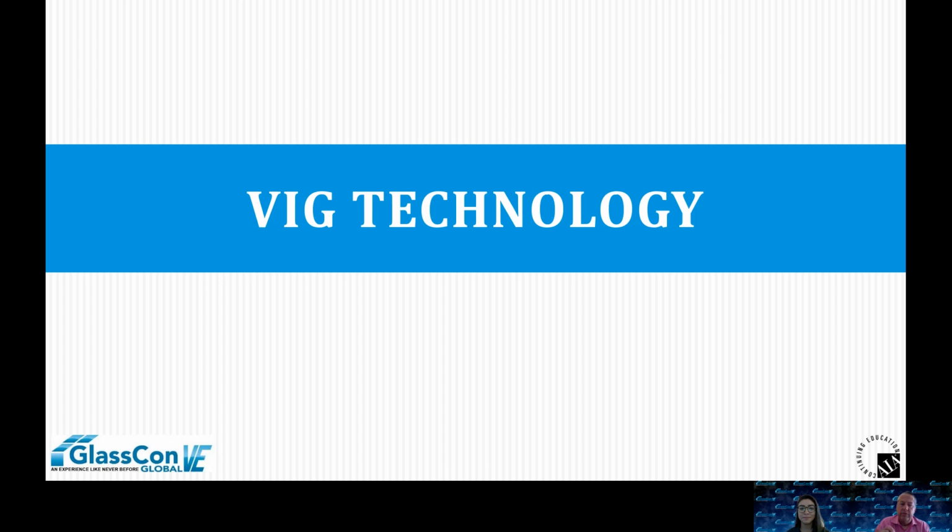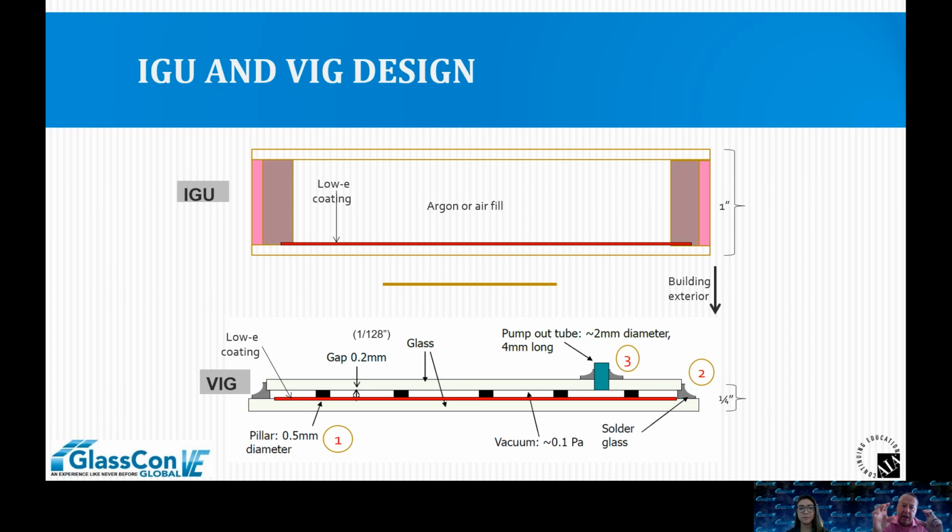Yeah, so first I'm going to talk a little bit more about VIG technology to make sure everybody really understands the difference between traditional double glazed insulated units. Again, it's the same two pieces of glass, but if you just took that traditional IGU and pulled a vacuum on it, the panes would suck together, the edge seal would kind of blow in, and your glass would touch, and you wouldn't get any of that insulation value. So there's a few tricks, and really it boils down to three things on how you define VIG and how that's constructed that are really important.